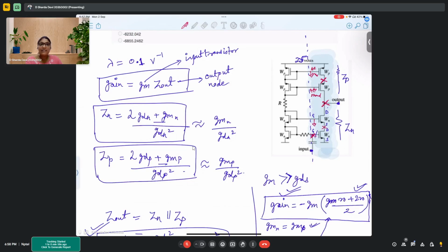So that is the reason we don't go for this mirroring side to solve it, because we know that it is complicated. And we also know that on the opposite side, if I find the behavior, since the circuits are just mirror images of one another, the response is a mirror image, so I can apply the same behavior to the other side. So that is the reason we go by solving the right hand side half of the circuit.